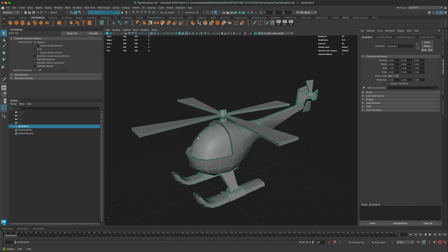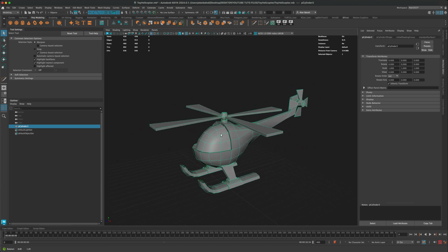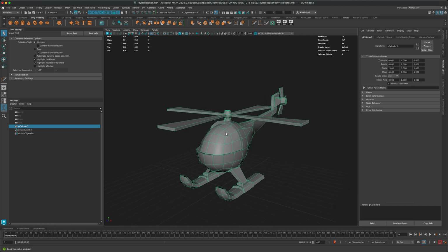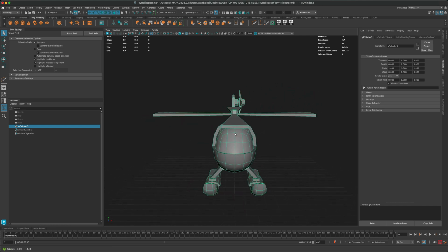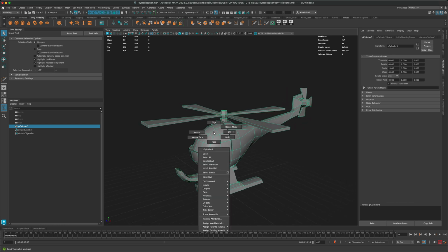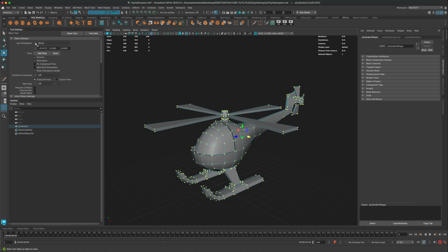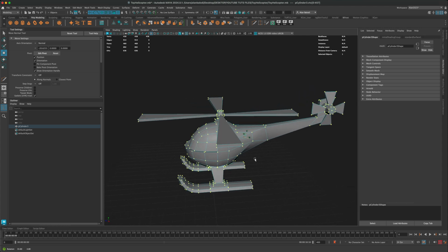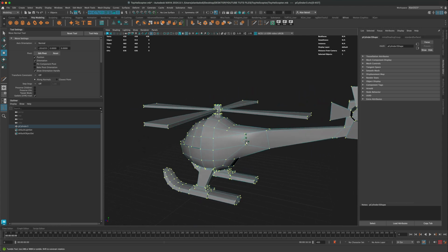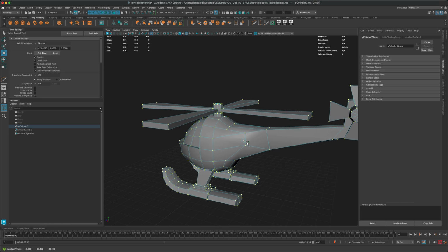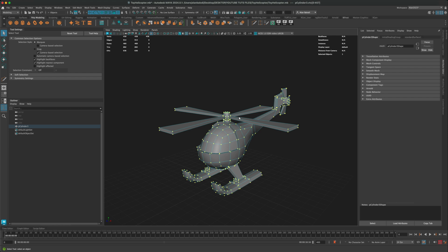At any point, if you wanted this to be maybe puffier, right? Like in my case, maybe I want it to be a little puffier as a toy helicopter. One thing you could do is just select all the points and then go into transform, switch it to normals, and now find the letter N and just scale this up or down so you can control the thickness of your helicopter even after you modeled it. So kind of essentially inflating it, right? In my case, I'm gonna make it just a little bit thicker so it's even more toy-like.